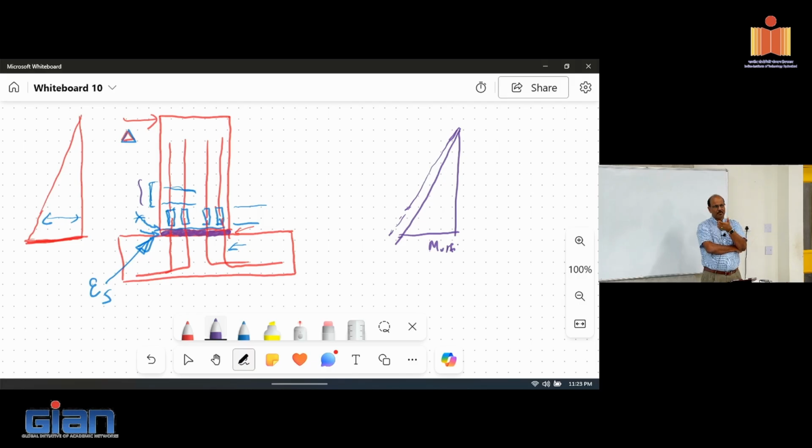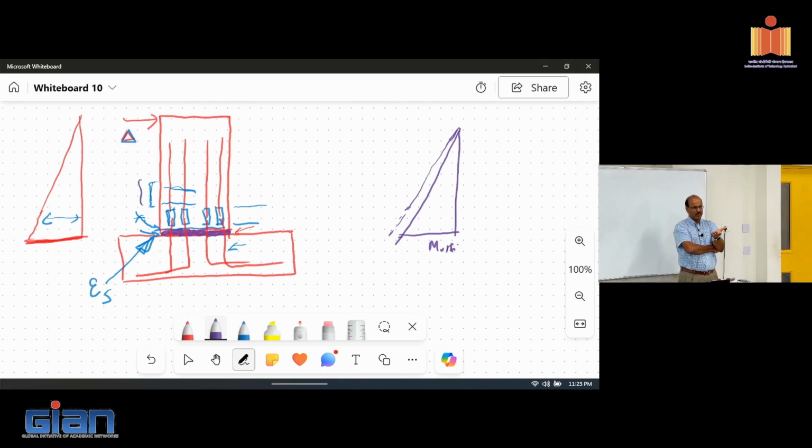If they are primarily bearing walls, gravity-supported walls, then there's no reason to have too much reinforcement, so obviously the minimum reinforcement governs. That's what happened in New Zealand. They will just drop the wall. These sleeves could be as long as 1 meter, so there is no crack whatsoever except at the interface. Once that opens up, your minimum reinforcement theory goes away because you really don't have enough reinforcement there, and they yield.